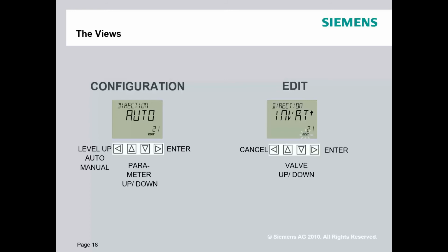There'll be a tag on there with its maximum allowable working pressure, and you need to put your air filter regulator in. You're filtering that air. The other thing is you're making sure that no matter what happens, I don't exceed that. I generally back it down about 5 pounds below that, and then I feel pretty good about that.